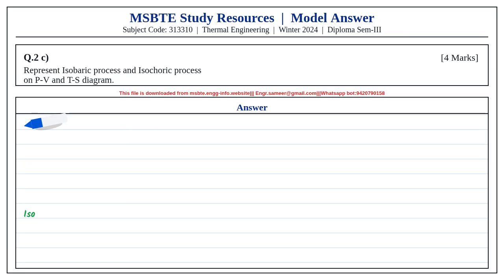In reaction turbine, steam expands partly in nozzle and further expansion takes place in rotor blade passage. Relative velocity remains same in impulse turbine while it increases in reaction turbine.